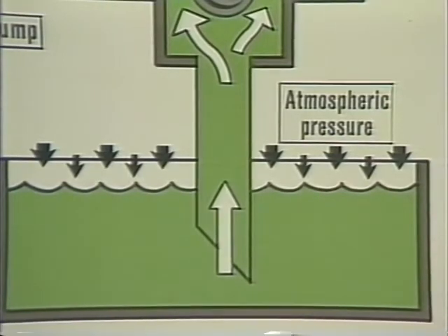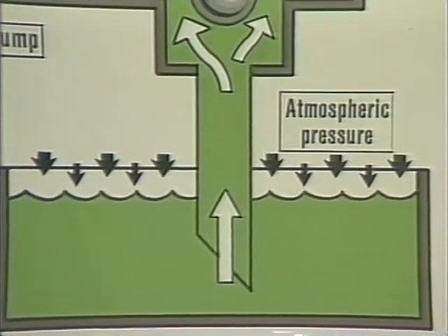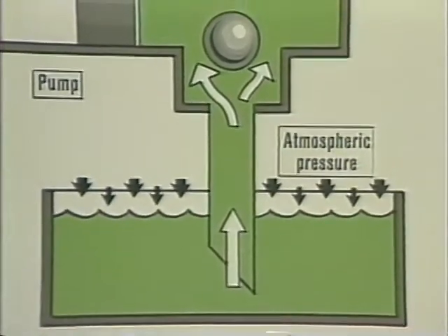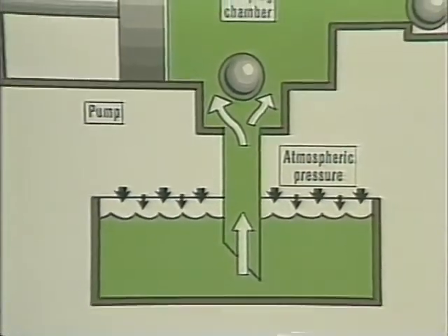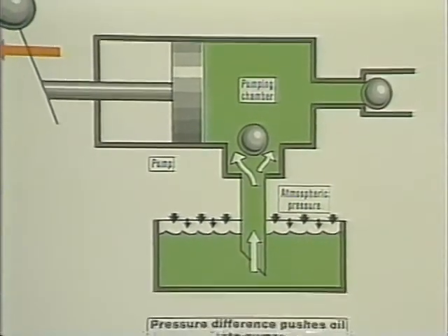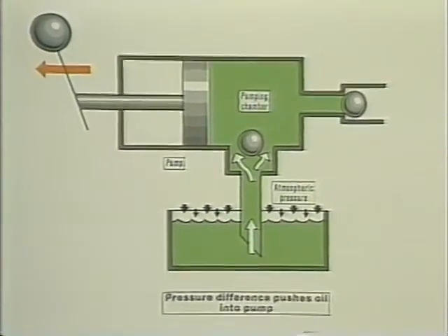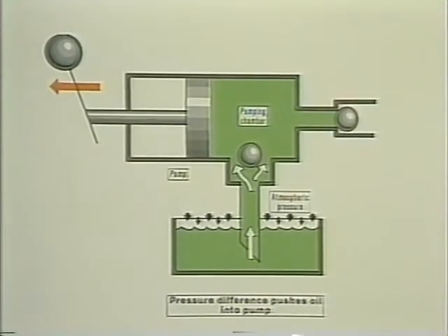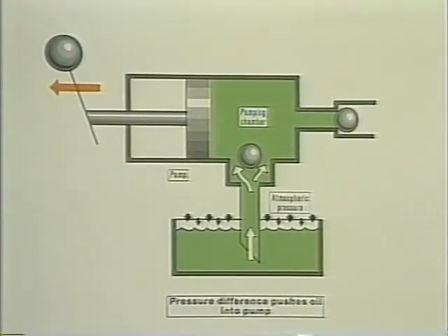Another thing, a surprising number of people, and probably some of you, think a pump sucks the oil out of the reservoir. It doesn't. A pump merely lowers the pressure at its inlet, and fluid is pushed in by atmospheric pressure acting on the surface. Inlet lines are especially important because with only 14.7 psia doing the pushing, any restriction or even too thick an oil may cause the pump to starve.